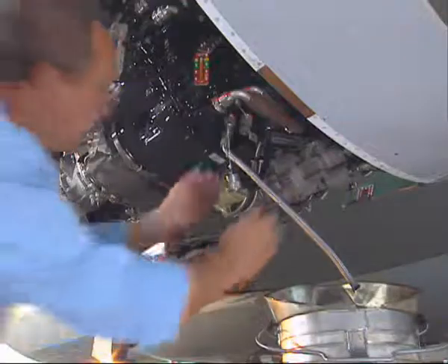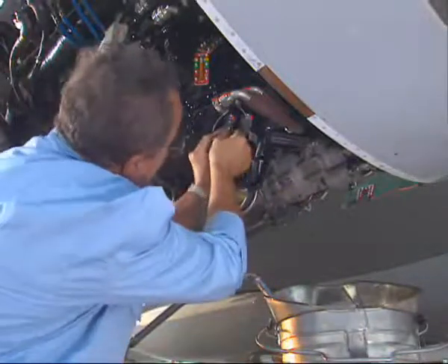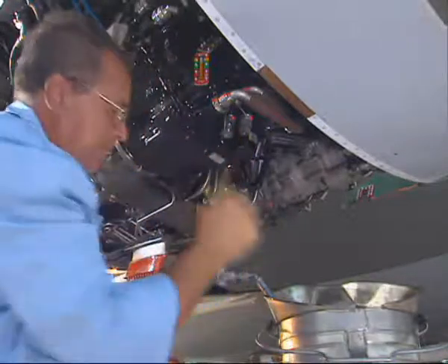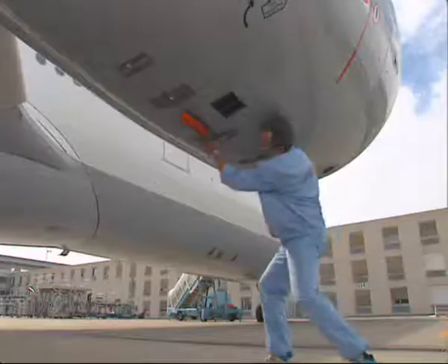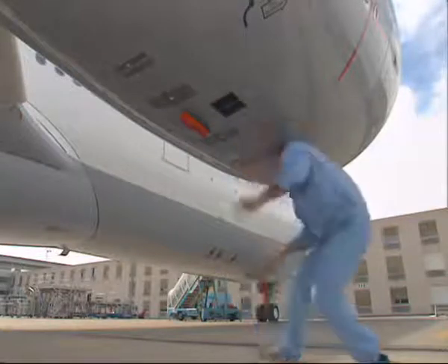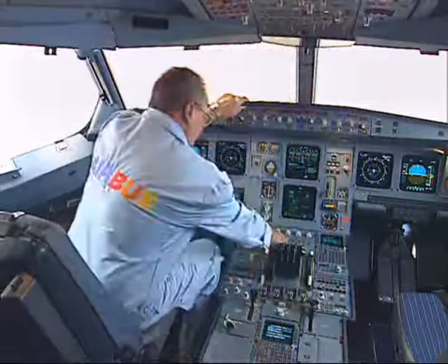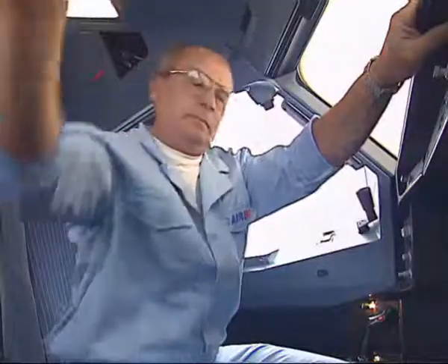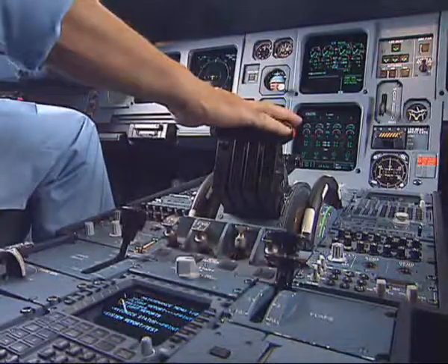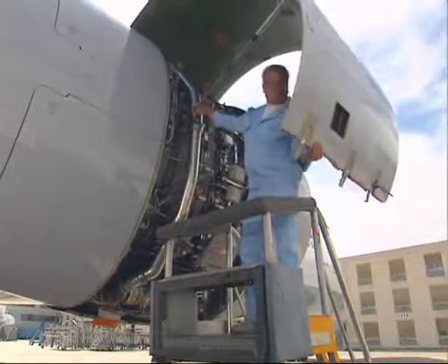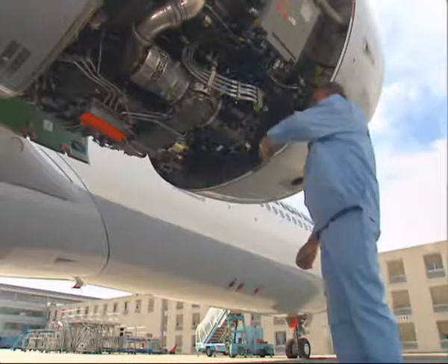When only drops of oil come out of the overflow drain hose, remove it. Install the dust cap on the overflow drain port. Do an engine dry motoring or start the engine at idle for at least 2 minutes to allow the oil to circulate through the system and ensure that every cavity of the oil system is properly filled with oil. Let the oil level settle down for 5 minutes.